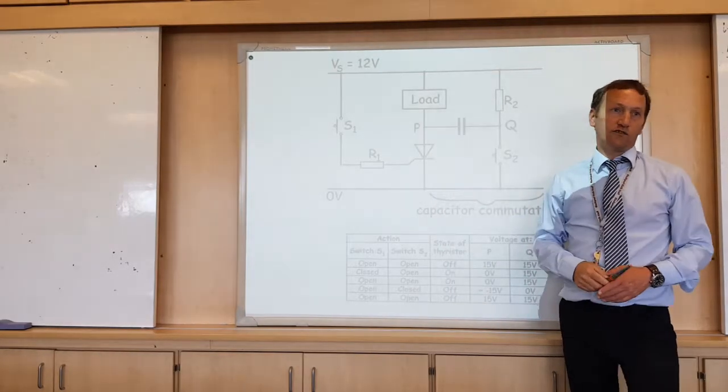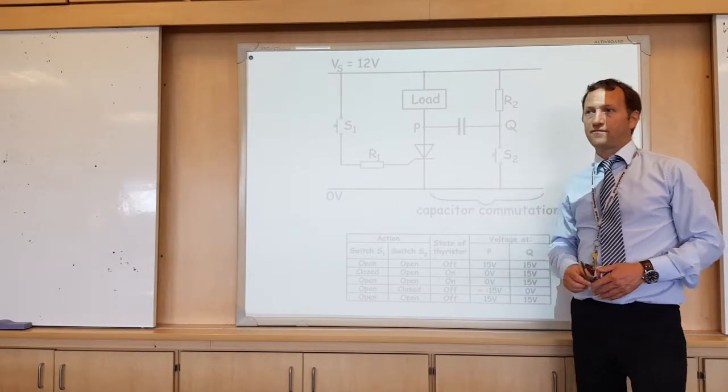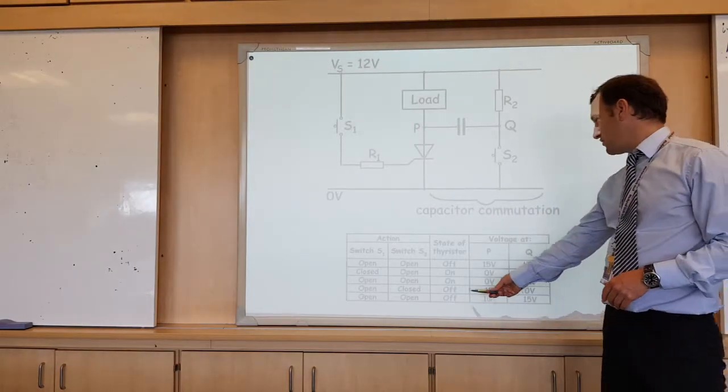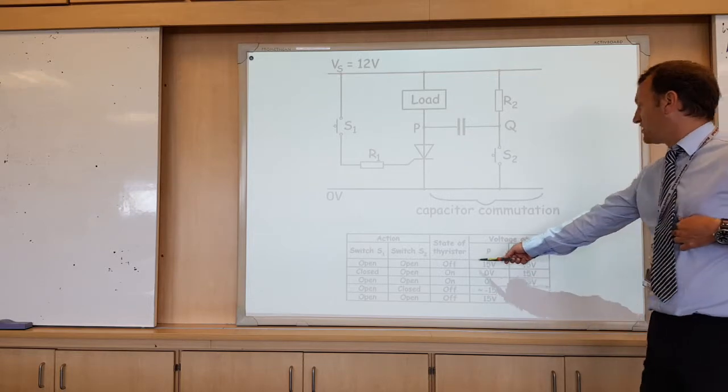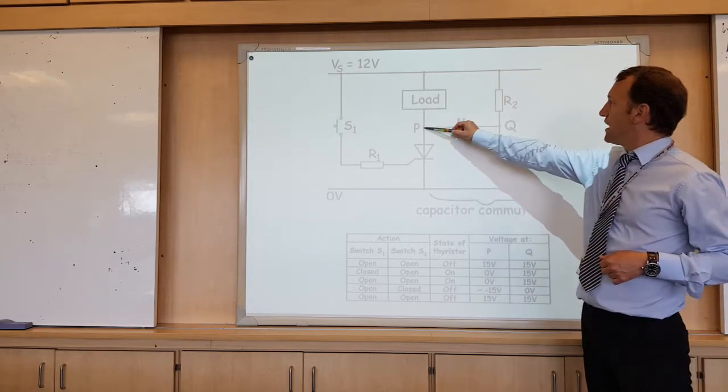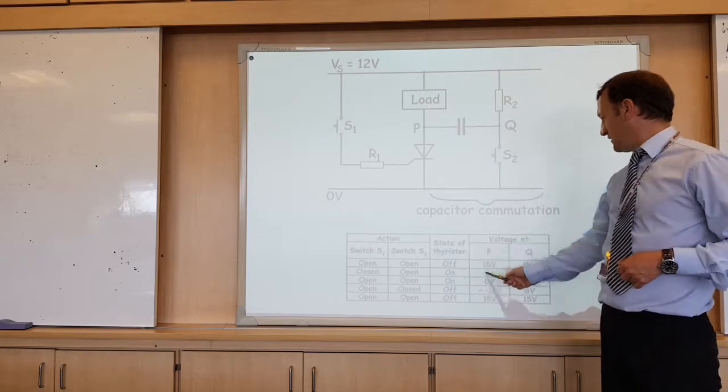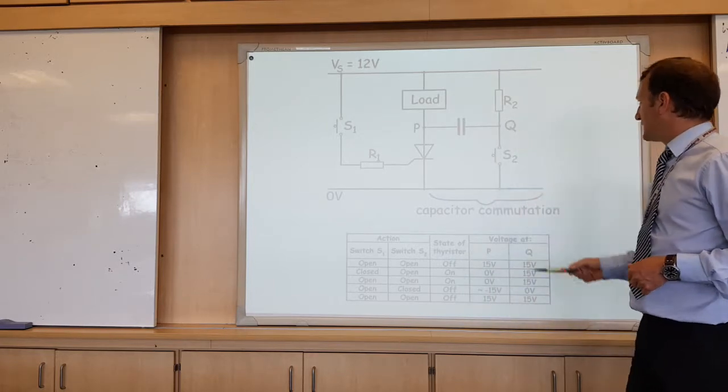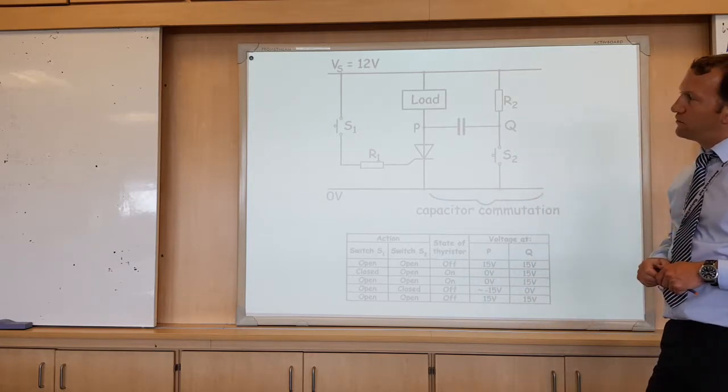That means the holding current stops and it unlatches. Okay? Then it goes back up to the state you started off in the beginning. So that will go from minus 15 up to plus 15. And then that will settle back down at 15 as well. And you're back to where you started.